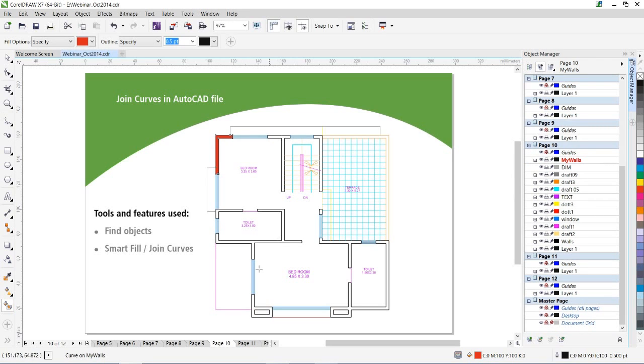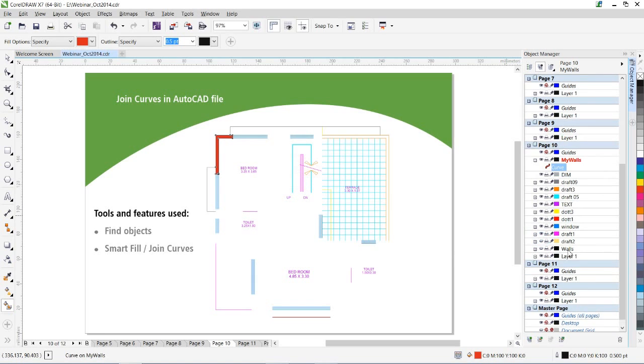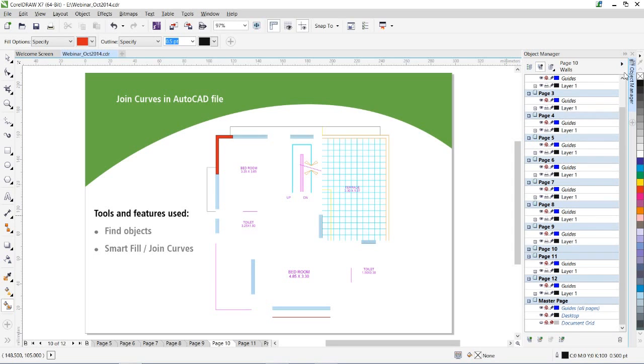Once I finish with all of the walls, filling up all of the walls, I just go and edit this original walls layer which the architect has created, or I just go and safely delete that layer. But the thing is, the user will have to know about using the layers. So there is another way you can do this, with join curves.